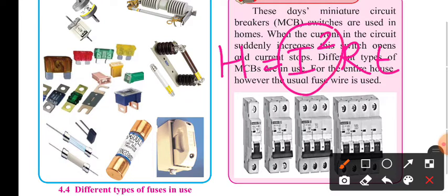So you can see here the relation between H and I. It is the square of current, so for 2 ampere, if the current is doubled, what will happen? Heat will increase 4 times, because we have the square of current. So as more and more current is drawn, more heat will be produced in the electrical conductors, the electrical wires we have at home. With that more heating, there is a chance that the rubber coating or the plastic coating on the conductors will melt.